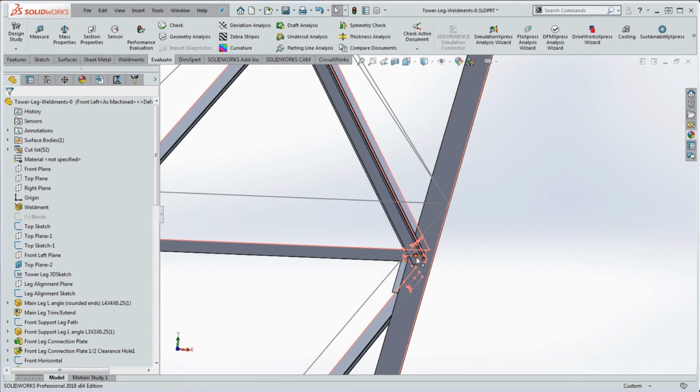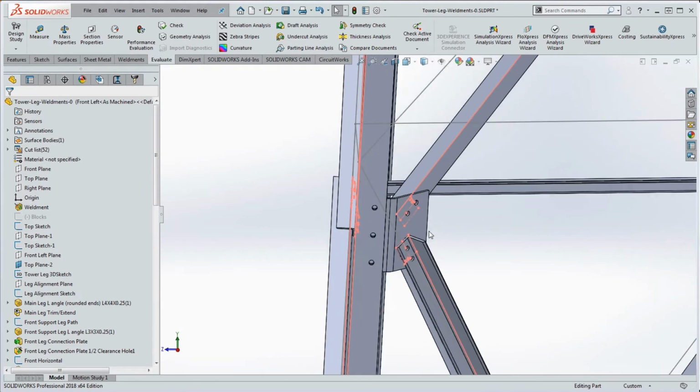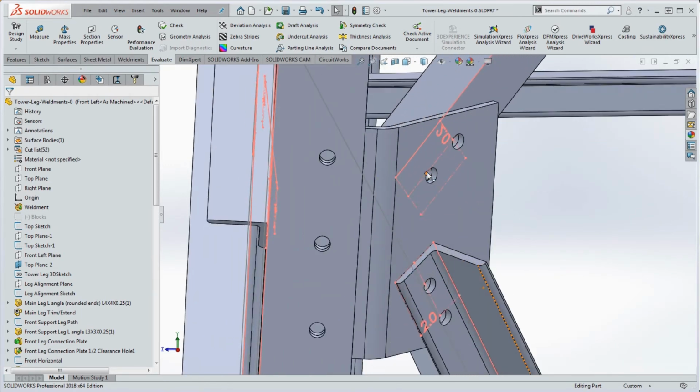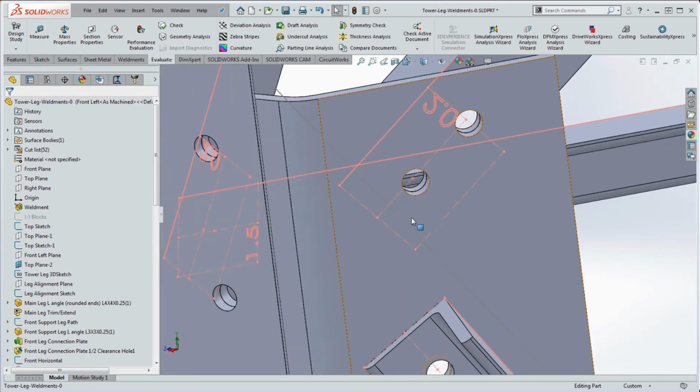The hole changes just slightly. That 1.5-inch horizontal stretches too, because it actually compresses a little bit, because it's actually going down. This connection plate in the back over here, that moves too. We have a diagonal off that on the front and the back of that. All those change too. And the thing about these alignment points in here that I didn't really discuss before in that sketch block, these are well-defined points. So this point is actually 1 inch from the very edge of our structural member that is going to get put in place. And we could change that. We can go into that block and make changes in that block, and everything will change.